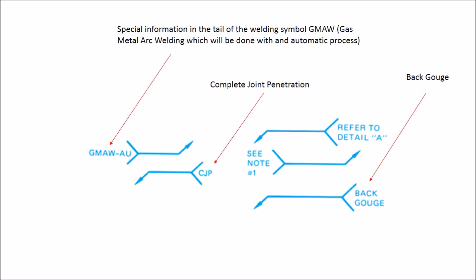A note is added to the print that specifies this option. The welding symbol may not always be adequate to denote the weld required, such as skewed weld joints that deviate from the straight line. When this is the case, a cross-section or detailed drawing of the joint and shape of the weld is shown on the print. Data in the form of notes may be added to the drawing to further clarify the joint to be welded or weld required.